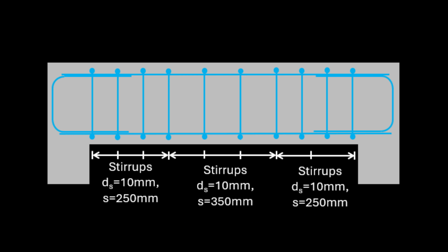Another thing you can optimize is that you actually increase the spacing in the center of the beam, because that's where the shear force is much smaller than close to the supports.